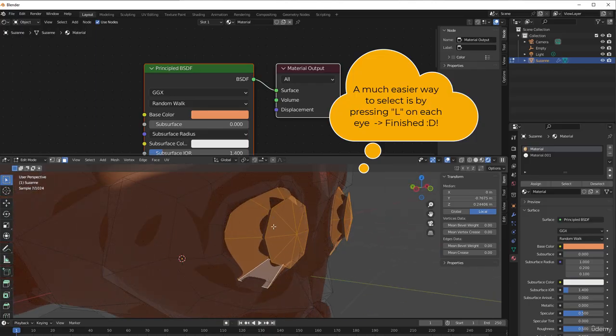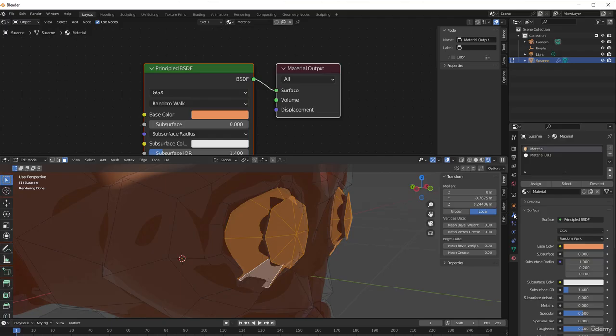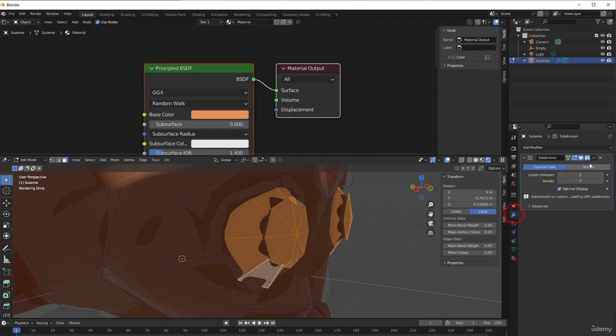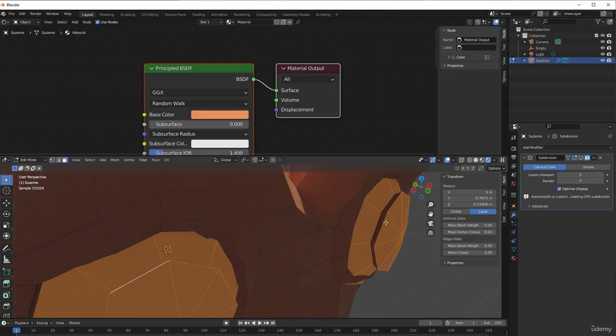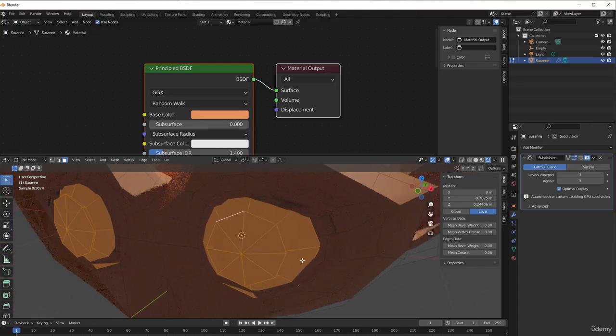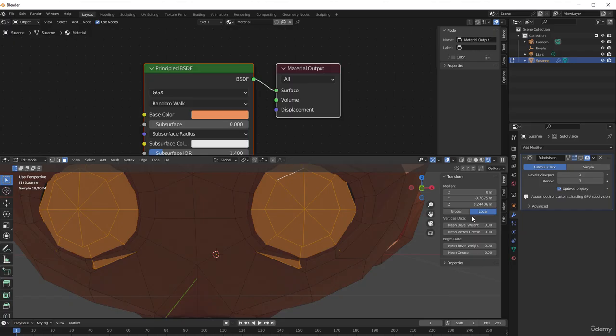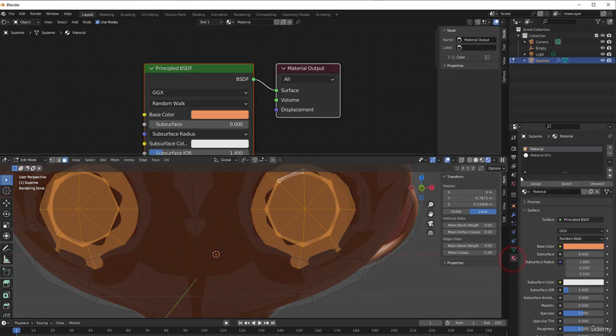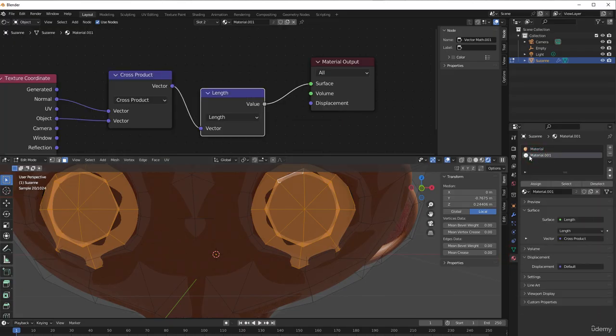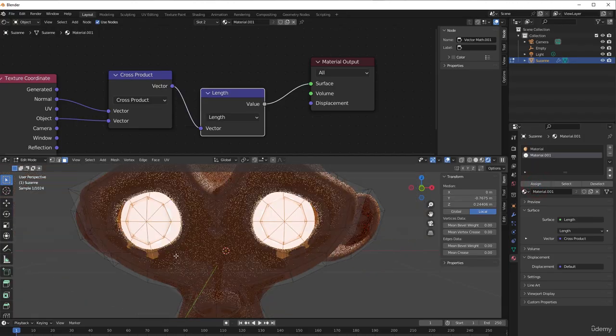I think there are even more here, so we can do it like this, that we take away the modifier property, or we unlock it so we don't see it. And then we can press Shift and Alt. Just select that one again, and take Shift and Alt and select that part again. So now everything is okay like this, and now we can activate subdivision again, and now go back to your material, select the material with the cross product in, and press assign. So now we have that in here.